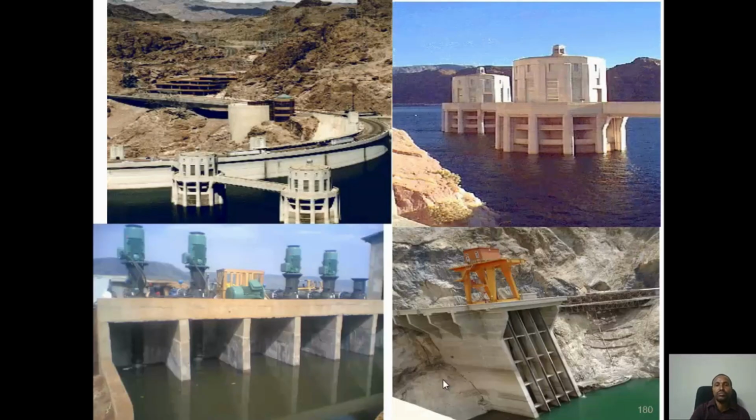So let me show you. These are intakes, tower intakes. You may have different tower intakes, two or three, different service intakes or main intake, and you can provide an emergency intake. These are walkways from the dam crest. You come, then you go inside, just for inspection purposes. You go inside, there is a tower, and you can maintain and also inspect, etc.